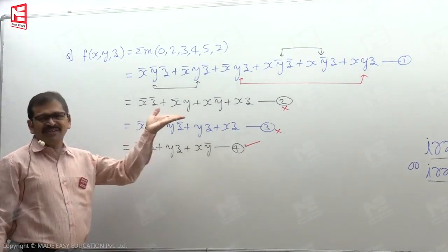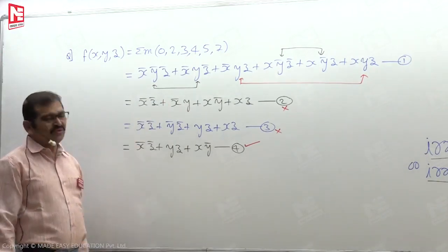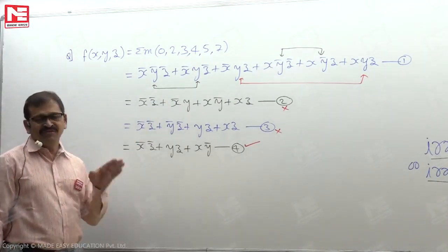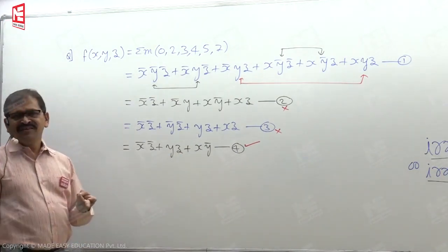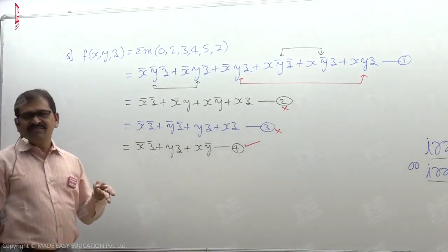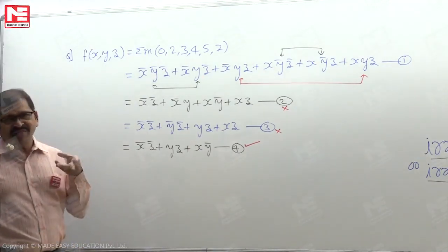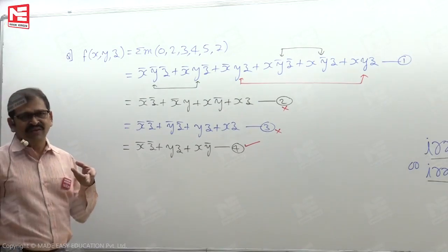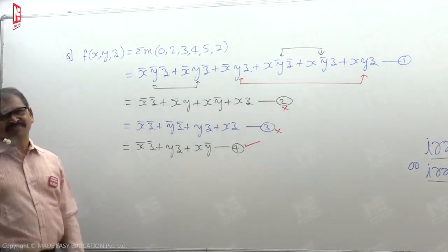It is basically a 2-level circuit as we discussed earlier. So at level 2 we need an OR gate with 4 inputs, whereas here we need an OR gate with 3 inputs. We learned that as the fan-in of a logic gate is less, that is, the number of inputs is less, the cost of the logic circuit is less.